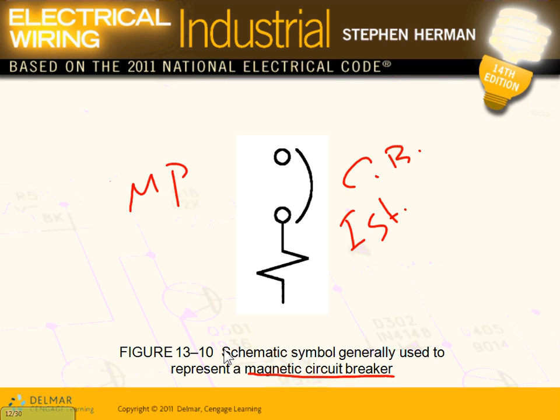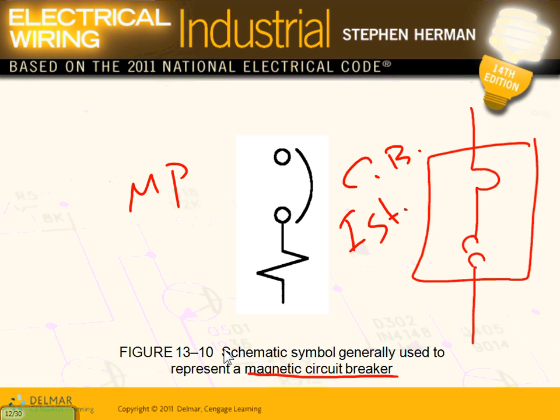A lot of manufacturers, you know what they do? They have this type of circuit breaker with a specially designed overload and a contactor. They put the contactor down here, and they make a starter. This is the commonly used instantaneous trip circuit breaker. Why? Because you put an overload with an instantaneous one tied to a motor, and together they act as what? They act as a thermomagnetic circuit breaker. So just be aware of that one.